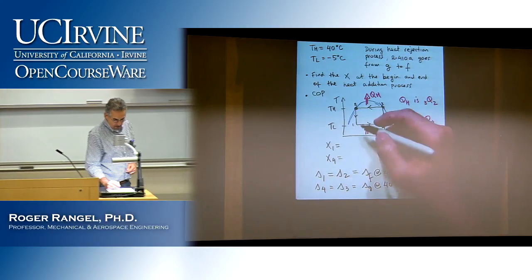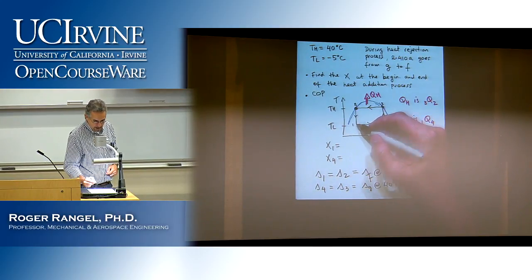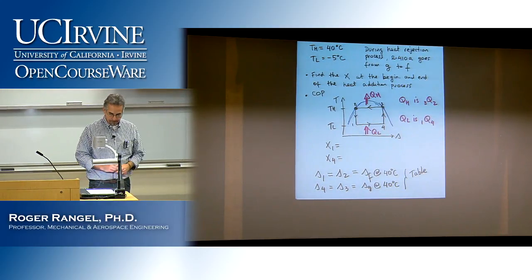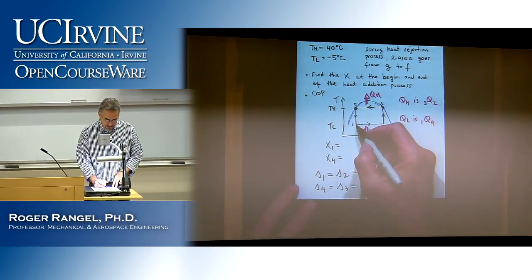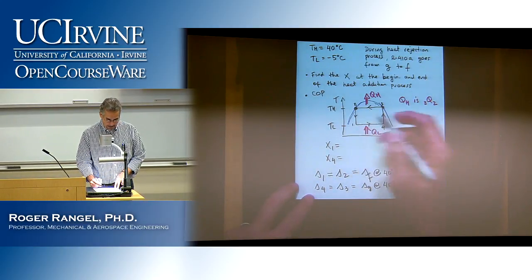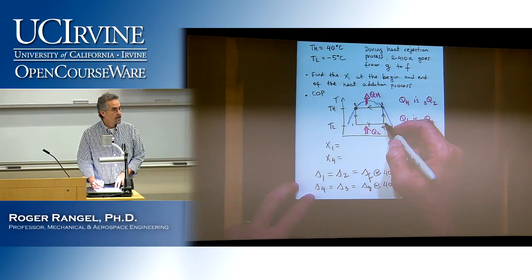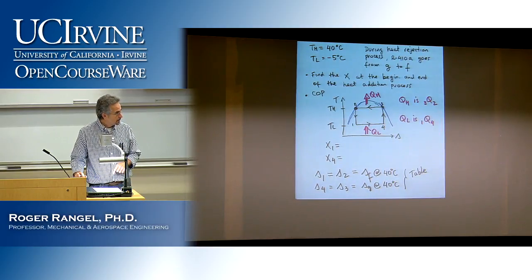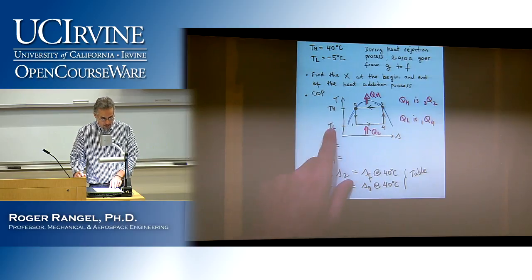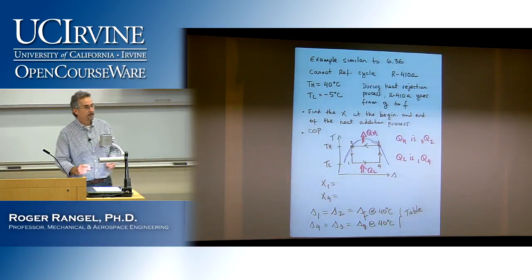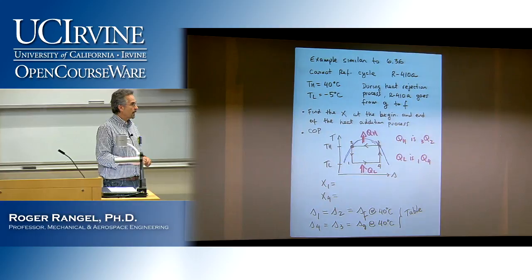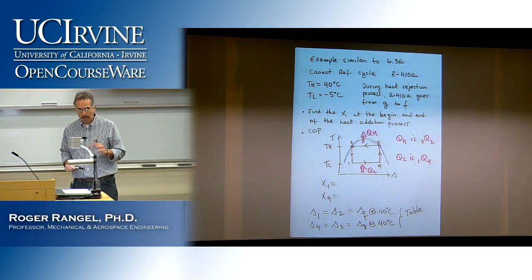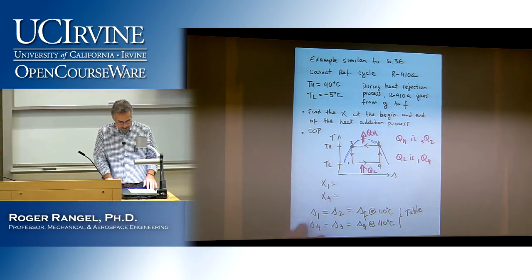And then, of course, I know those are actually the entropies at 1 and at 4, respectively. Right? And so once I know the entropy at 1, and I know the entropy at 4, I can go back to the table to read SF and SFG, but now at -5, to get my quality at 1 and at 3. So I'll let you finish that.